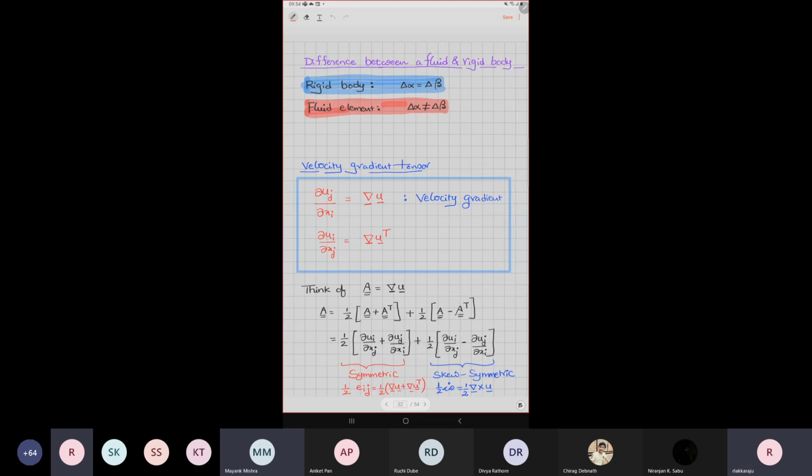So typically people try to quantify two elements: a body, whether it is spinning without any angular deformation, what we call rigid body rotation. If it is not spinning, you take a book and try to spin it. That is what we call rigid body rotation, where your delta alpha, delta beta are always the same. There is no difference. But whenever there is a variation on this axis, delta alpha, delta beta is going to change. That means it might be getting a shear kind of deformation.